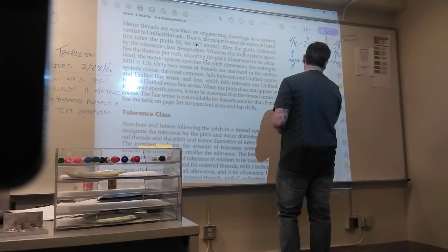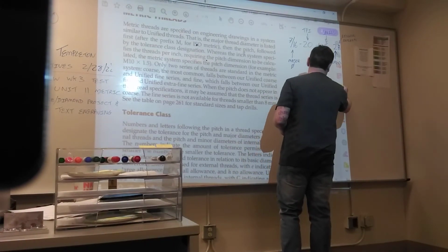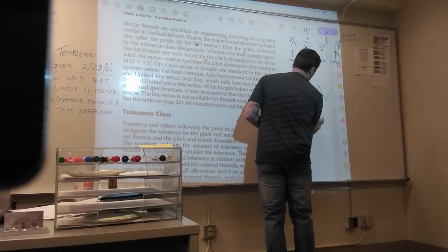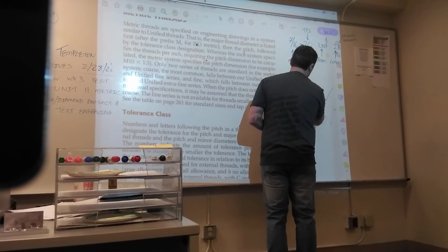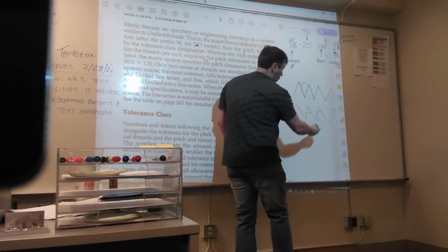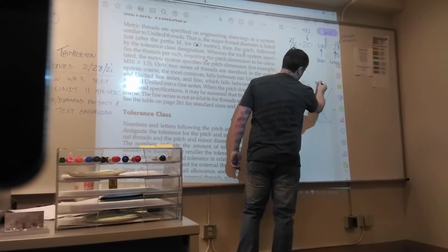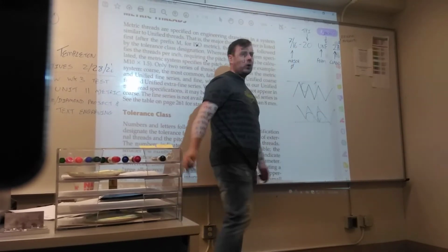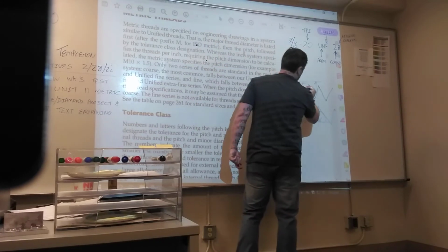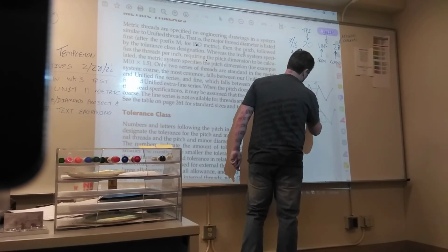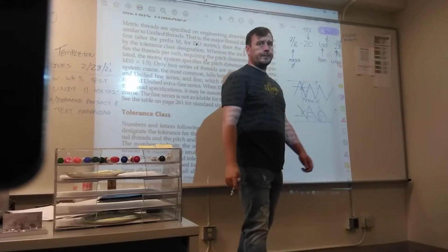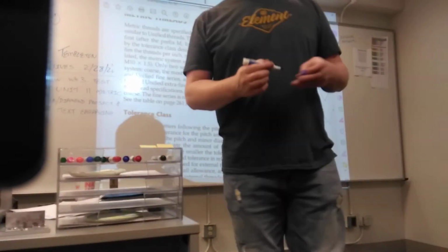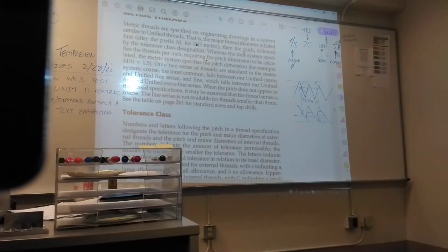So on the threads, you put in those wires in here, right? And then you put your mic over the top and get a measurement. What you are actually checking is here, the middle, which is called the pitch diameter. So when you look in the book, that gives you the tolerance for your pitch diameter. How much tolerance you got when you use those wires.